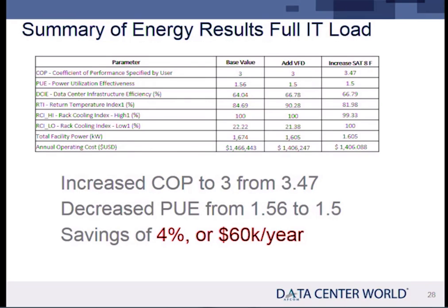The other problem in cold aisle I've seen as well is that you get temperature variations in it. Because it's a small area, if you have servers that are stacked a certain way, it'll blow by the first one, and the second one will grab it, and the first one starves, and you get hot spots in a cold contained data center because the servers are not uniform with respect to the fans. They're all running a little bit different. So I have seen a number of issues with that.